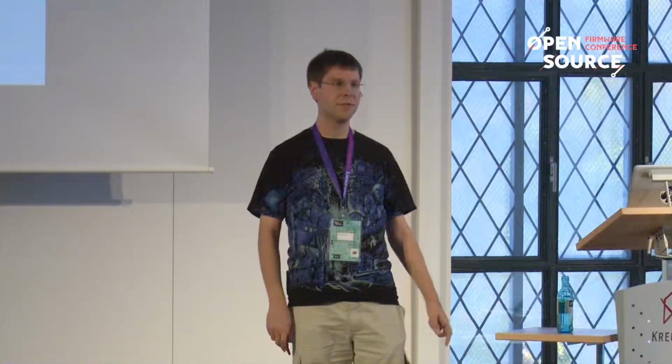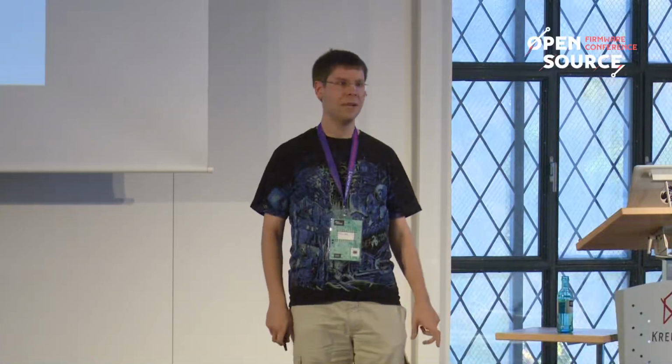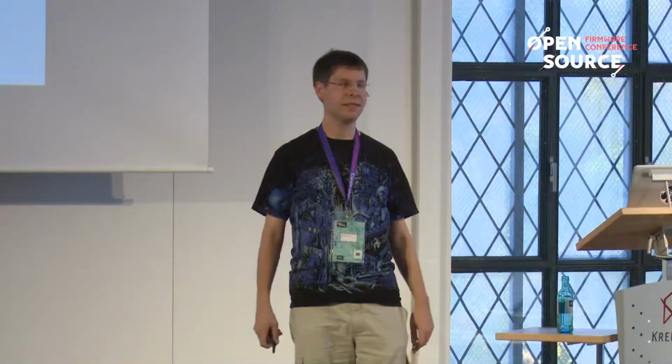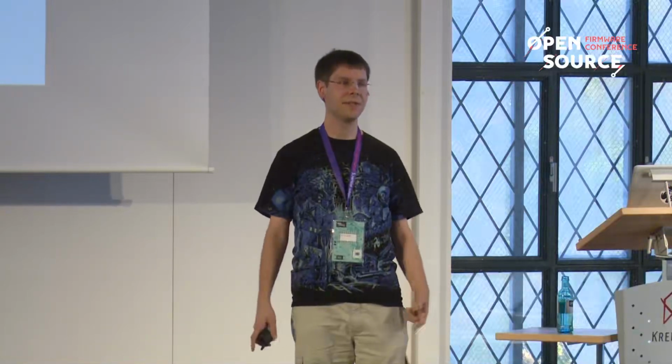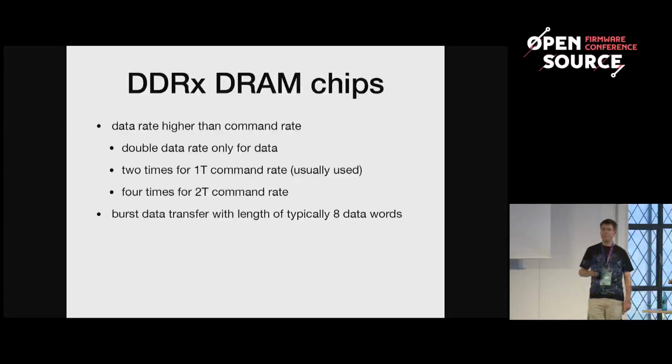Another thing that's done there is for registered memory. To support more memory, basically a small chip is put in front of the command bus, which is more or less just a redriver for the signals, or basically it reduces the bus load when having multiple memory modules.